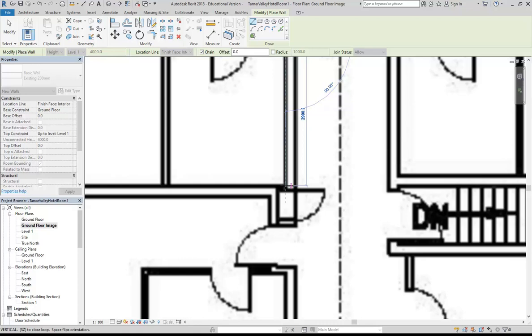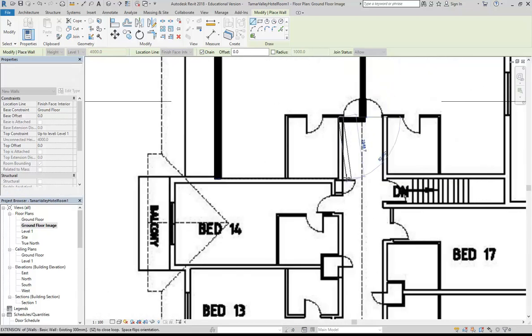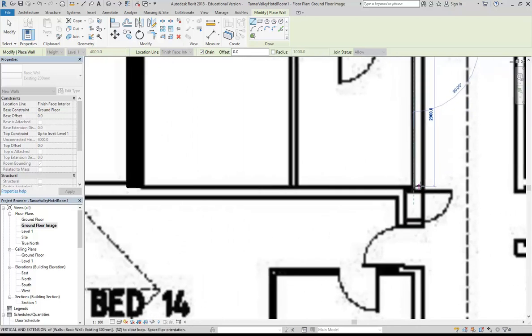Yeah, that's right. That's the starting point. So you definitely need a different wall thickness for the exterior wall and then the interior wall. But then what about the walls between the units, between the hotel rooms? So they need to be different again. Yeah. So they're essentially party walls, that's right. So that's the 230 wall. So that's really important that you indicate those different thicknesses.